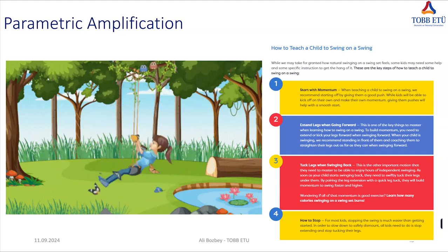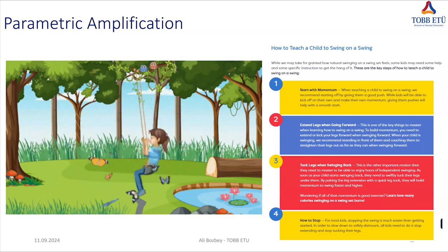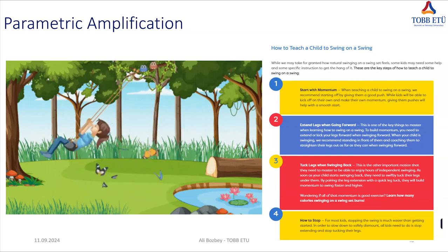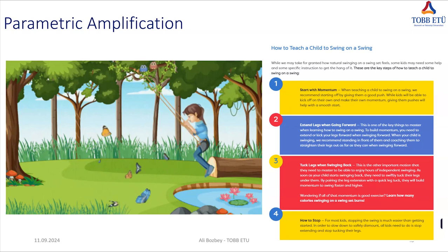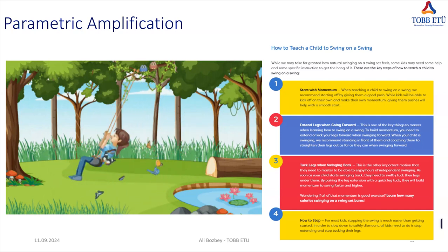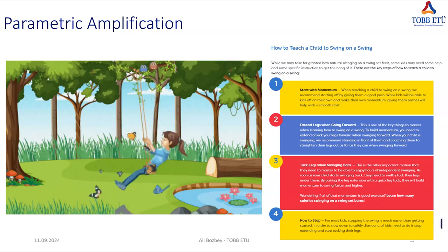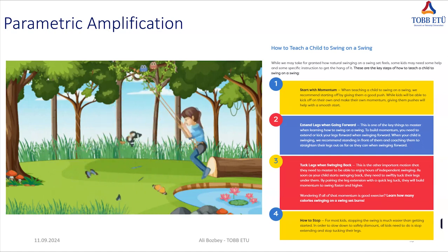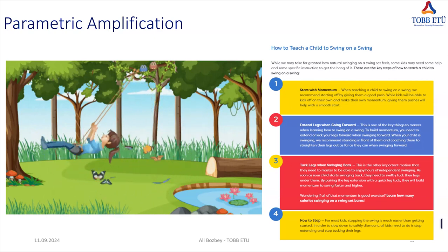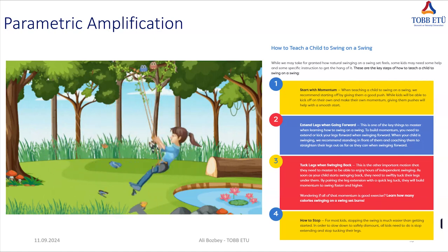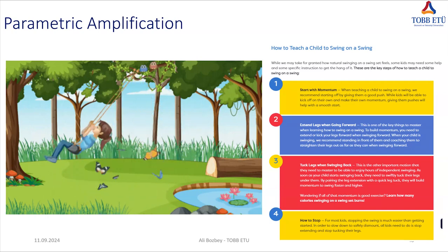Because just after the qubits, there are parametric amplifiers based on Josephson parametric amplifiers or Josephson traveling wave parametric amplifiers. They are quantum limited amplifiers that can operate at millikelvins. So before you go to the CMOS or HEMT amplifiers, you amplify your signals by about 20 dB. So it makes it possible to read out at room temperatures.